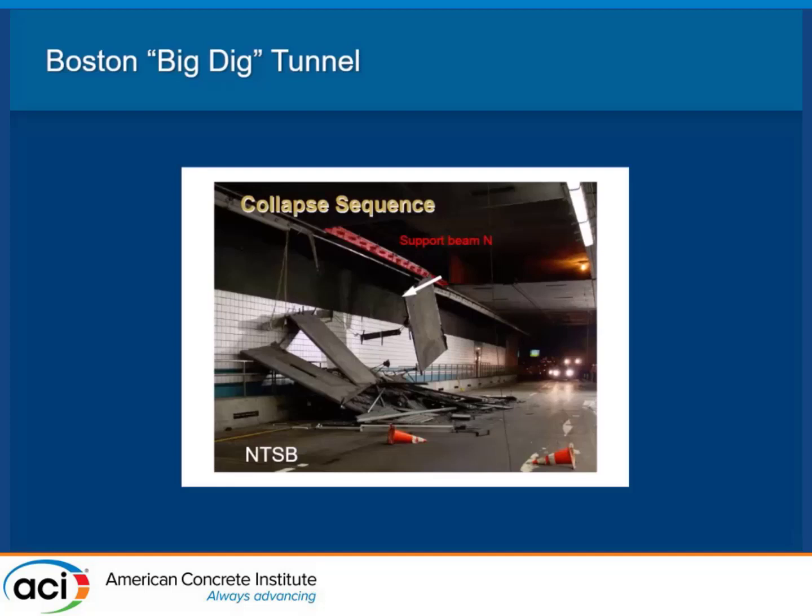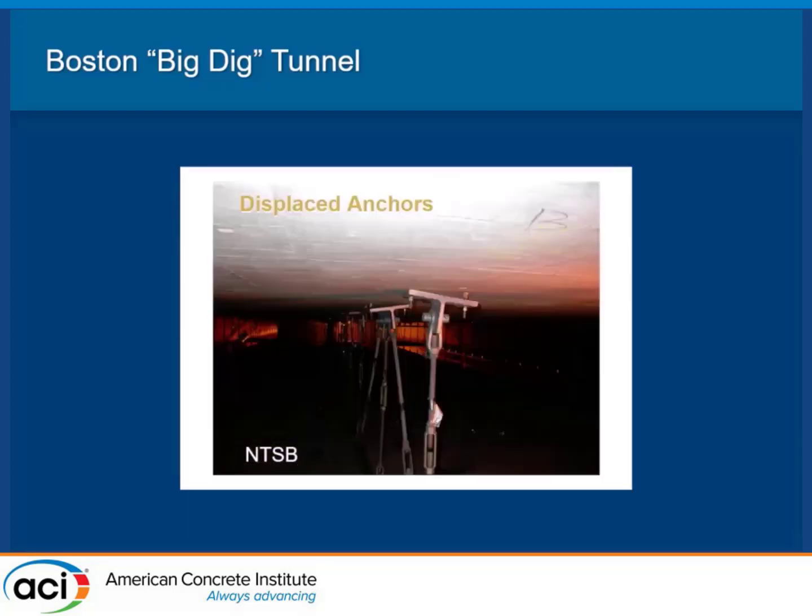The air intake is above the pedestrian walkway. The anchors supporting the end board and end of the exterior panel are the ones that failed. That is the anchors along line M. So for those of you around here, you know what that is, it was line M. Further investigation of the hanger support system found conditions like these shown here. The collapse occurred in the eastbound lanes. These photos are of the westbound tunnel in the D Street portal.